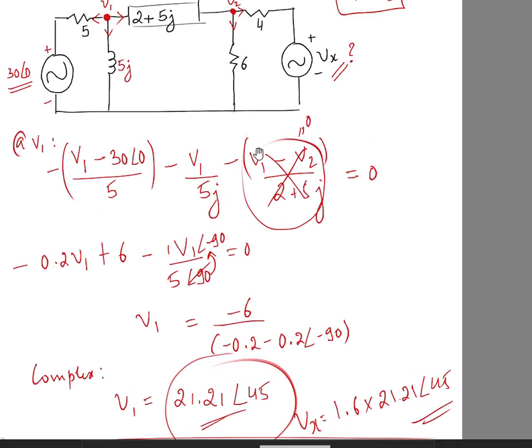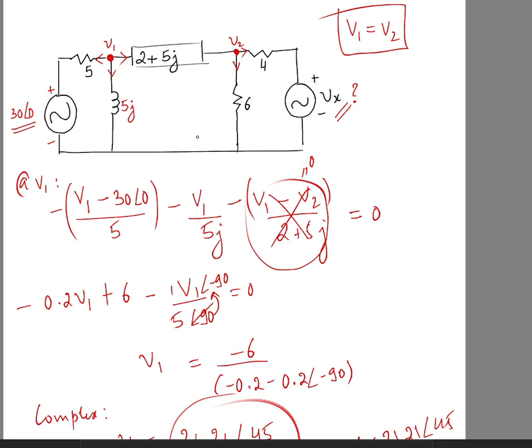Now whenever you have any j question, you solve it the exact same way you would solve a normal problem. But if you want to simplify it, you can go to the complex mode. If you want to change between rectangular and polar forms, you can press shift plus the plus button, or shift and the minus button. Shift and plus is going to open the polar window, and shift and minus will open the rectangular form, where you can enter the polar coordinates and it will convert them to rectangular form.